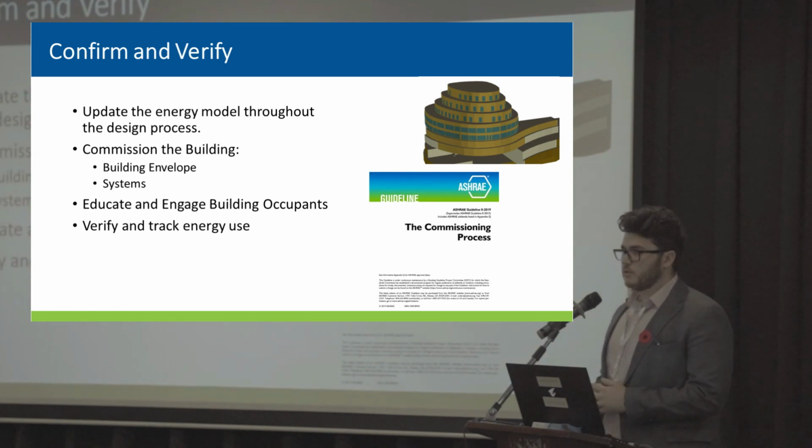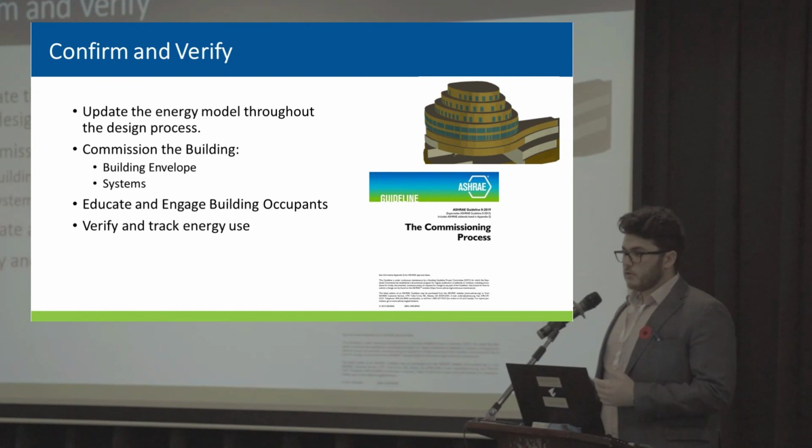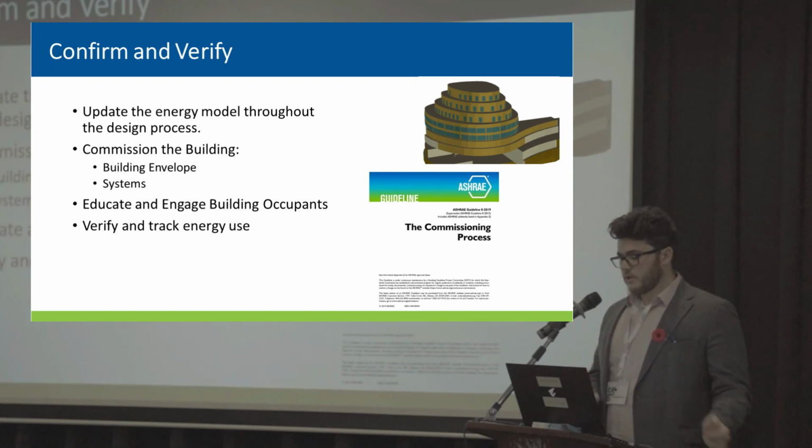The building cannot be zero energy if the occupants are not aware the building's going to be zero energy. So it could be through lighting, could be through motion sensors, could be through reminders or floor-by-floor challenges is a big thing that they put. And then you also have to verify and track that the energy use for that building is aligning with the zero energy target that you set at the start of the project.